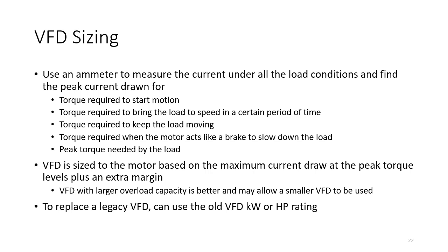Now generally we're looking at current, so amps. Amps is the parameter we should be looking at to size our VFD, but often you don't get the current that you require if you're replacing a legacy VFD, or if you're just looking at the motor nameplate, you might just see a kilowatt rating. So in that case, you could replace the old VFD just based purely on its kilowatt rating, or maybe it's got a horsepower rating. That isn't as accurate as using the current, but it would normally give you a VFD that's good enough. Possibly with modern VFDs, it would be oversized compared to the old VFD, but that's not such a huge problem by oversizing the VFD compared to oversizing the motor.